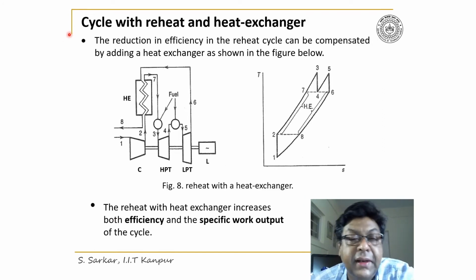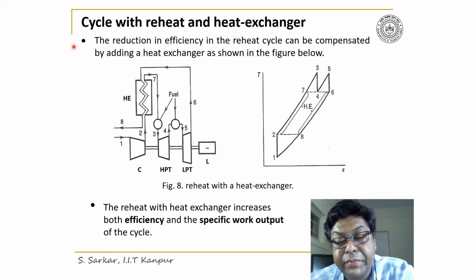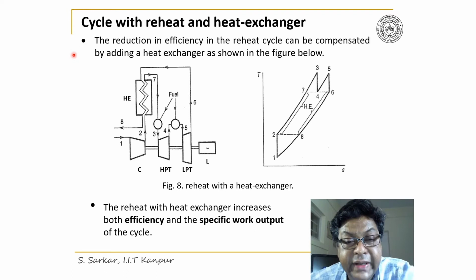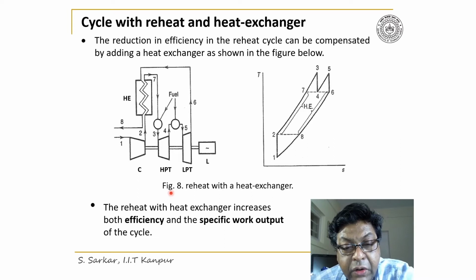I'll discuss cycle analysis with reheat and heat exchanger. I've already told that the efficiency of a reheat cycle is less than that of a simple gas turbine cycle. Thus, the reduction in efficiency of a reheat cycle can be compensated by adding a heat exchanger as shown in the figure. Thus, the schematic of a reheat with heat exchanger cycle has been illustrated in figure 8, where I